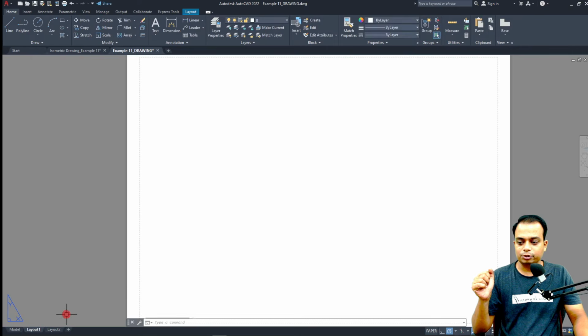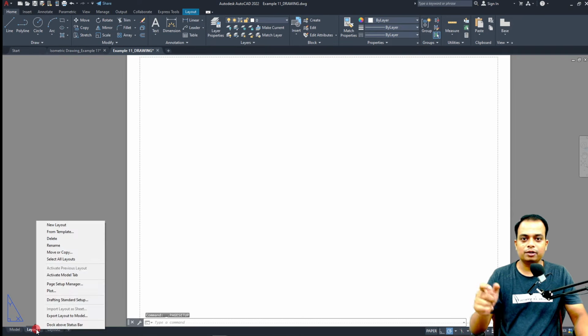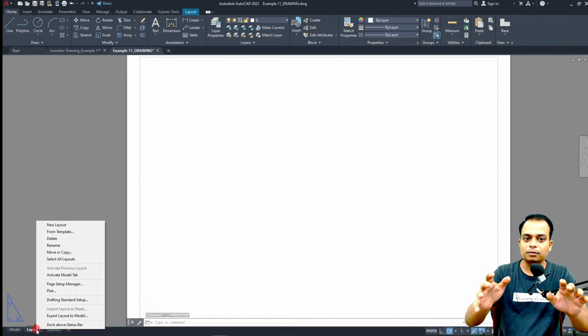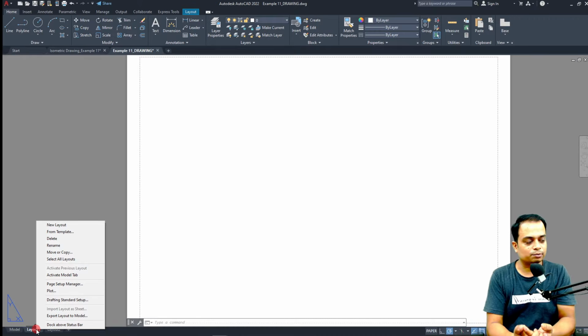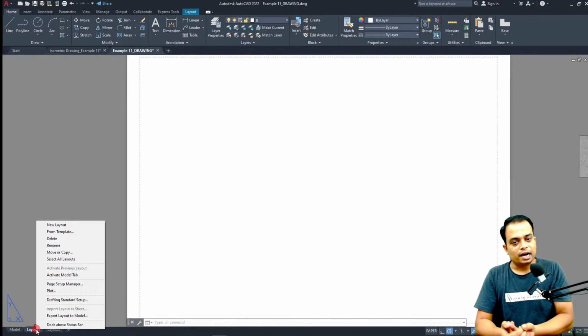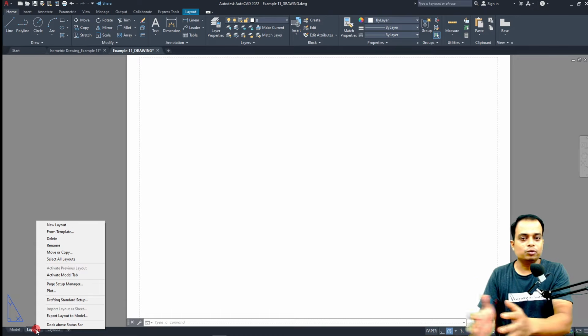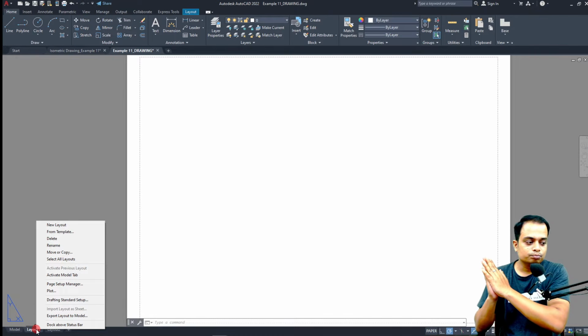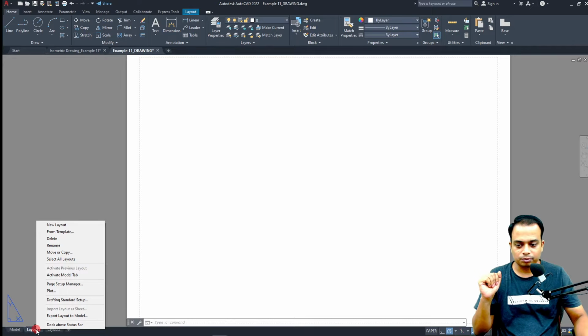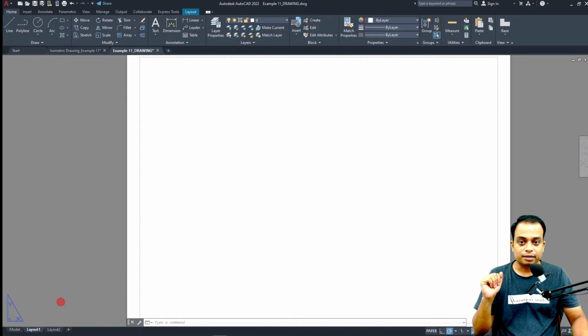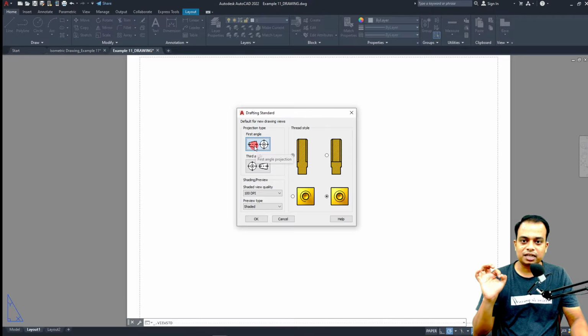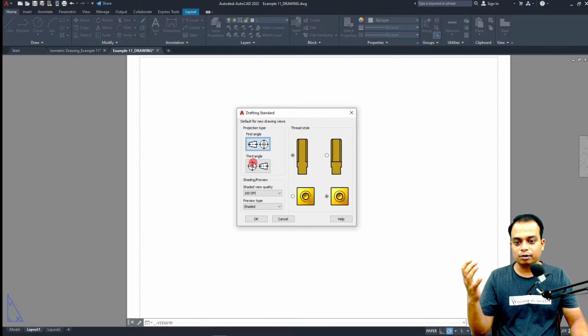One more thing that you need to check is right click on this. And by the way, you are also enhancing your AutoCAD skills by watching this video. Okay. And if you are making this drawing manually, follow the instructions. You will be able to do it without any hiccups. Let me be very honest with you. Go to drafting standard setup and check if it is set to first angle projection or not. Yes, it is. Okay. If you're handling an American client, you have to go for third angle projection.